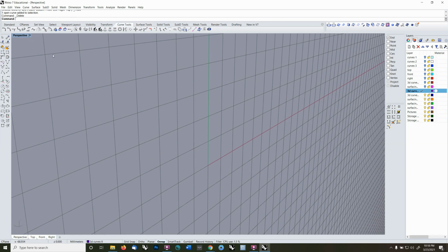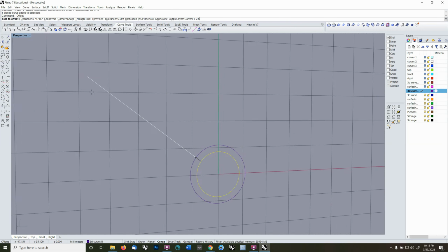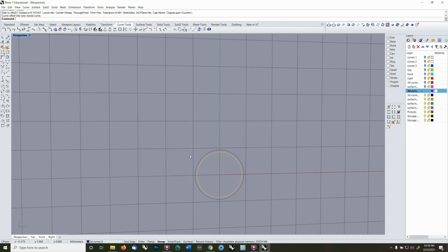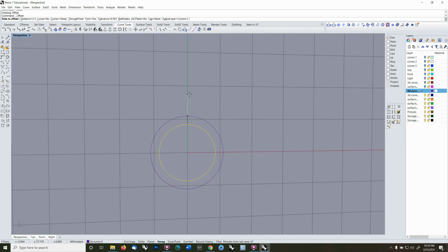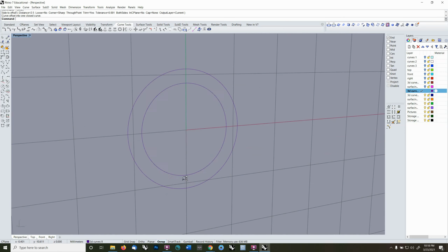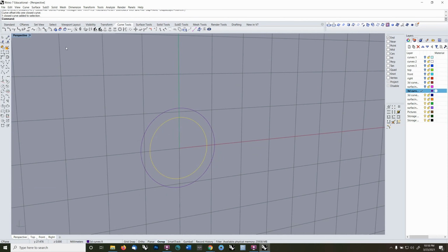Let's draw a ring shank. Zero for the center, diameter 17 millimeters because that's the standard. Offset at 2.5 because that's as thick as you want a woman's ring to be between the fingers normally. Offset this 1.7 because that's how thick you want it at the bottom if you're going to do a casting.